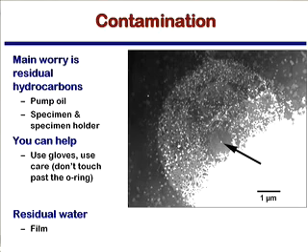And again, one of the things that you can do now is you can buy something called an Evactron. It's a system that just puts in an argon-oxygen plasma in the SEM. Okay? It cleans the whole SEM and your sample. It looks like they're about $15,000, and I'm trying to find a little bit of money to put one over in the Hitachi over at Berk for just that reason. So it just helps clean things up and minimize that problem. But carbon contamination is an issue.